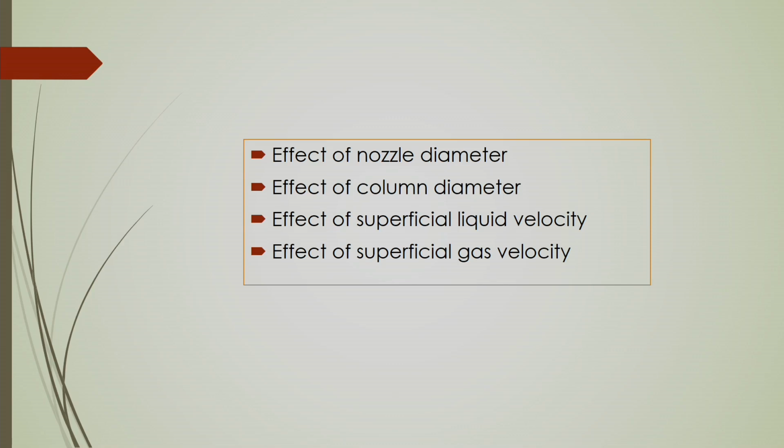Even if you increase the superficial gas velocity, there will be more dispersion of the liquid inside the bed, because there will be internal circulation, and even the random motion of the bubbles will disperse the fluid elements more. In that case, if you increase the gas velocity, the gas hold up increases, and if you increase the gas hold up, you get more actual liquid velocity inside the bed, because of which you get more kinetic energy, more momentum transfer, and more dispersion.